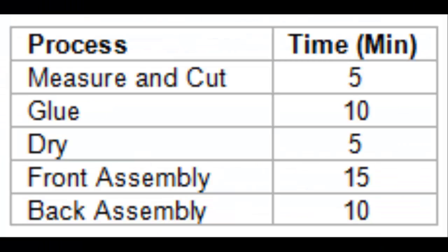After determining the forecast plan and how many items are going to be needed for manufacturing at what designated times, the next step was to analyze the manufacturing process. In order to do this, I designed a simulation of the assembly process using ProModel. The design manufacturing process for the Strider contains 6 locations: an inventory stage for both raw materials and partially assembled parts, a glue station to glue the carbon fiber to the aluminum joints, a dry station for drying the freshly glued objects, a cut station for measuring and cutting the carbon fiber into the desired lengths, and an assemble station for assembling the front and back wheel assemblies.